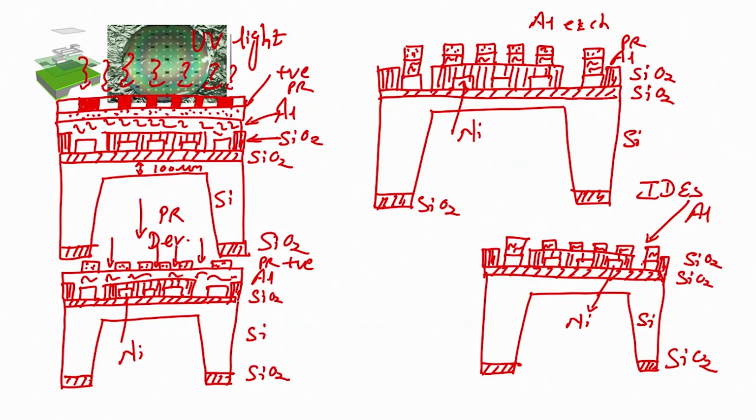Now, after this, what is the next step? Next step would be acetone dip. So, when I dip my wafer in acetone, I will have my interdigitated electrodes over insulator over micro heater over oxidized silicon substrate, and that is having a diaphragm. Still, we have not finished fabricating a VOC sensor.